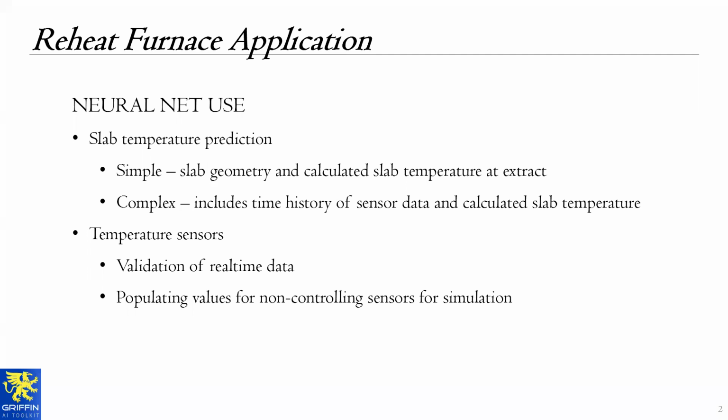Where this model tends to fall down is when you're transitioning between material types and also target temperatures. As you're moving around, that error term is basically going to change unpredictably. And that's where we were starting to see problems where if we're going from high temperature to low temperature or vice versa, it's taking longer than we thought, or we're dropping down too much in temperature and having swings.